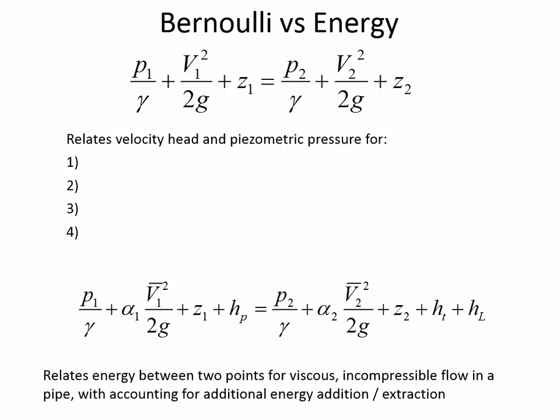And so the pump head, basically, it's like boosting the water. When we express it as a height, we're saying this pump is adding enough energy to the system that it's like it lifted the water in a way. So when we say the pump adds 10 meters of head, it's equivalent to if this pump had lifted the water up an additional 10 meters. So in that way, it kind of makes sense, right?